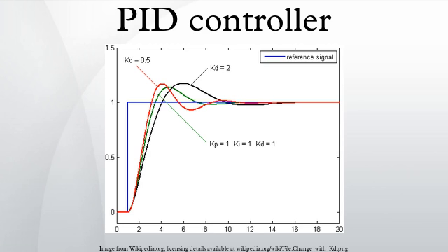In the real world, this is D to A converted and passed into the process under control as the manipulated variable. The current error is stored elsewhere for reuse in the next differentiation. The program then waits until dt seconds have passed since start, and the loop begins again, reading in new values for the PV and the set point and calculating a new value for the error.